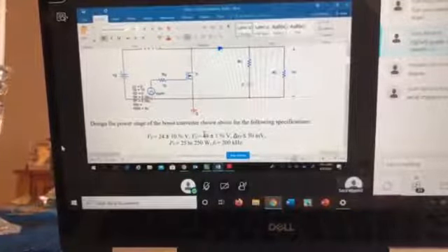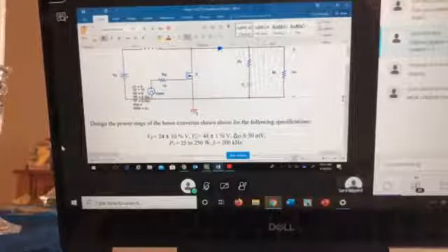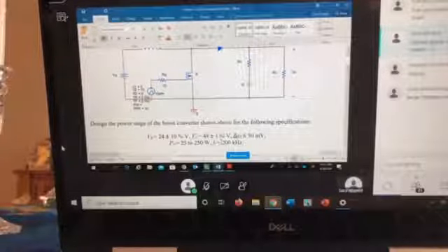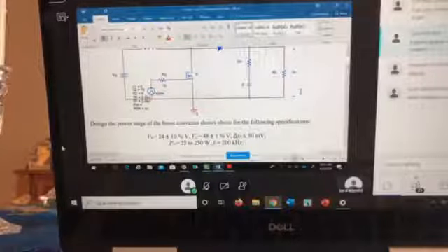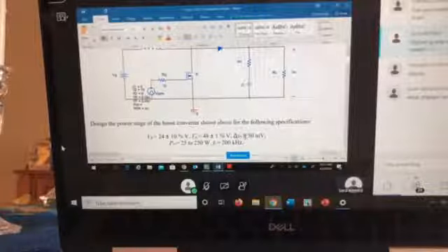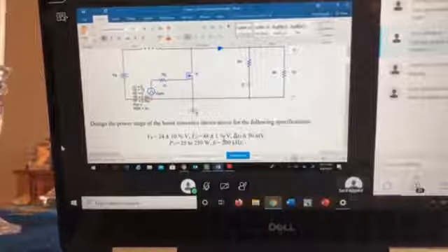But if you remember, we have a little bit of an AC ripple, so it cannot be just 48. It will have to have some ripples, and this 1% defines those ripples. Why? Because this ripple will be equal to this V out plus delta VO. Those two together, if you add them, will give you this 1% up and down. And that's where this 1% comes in.